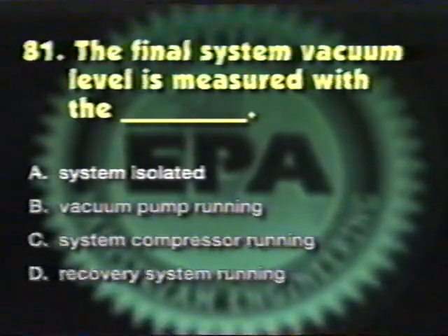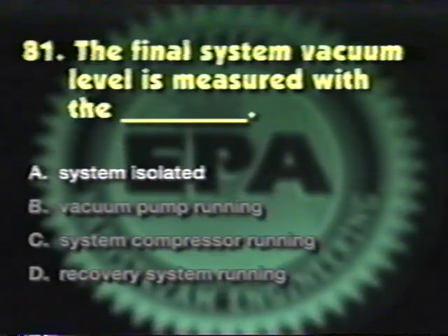The correct answer is A. The final system vacuum level is always measured with the system isolated and the vacuum pump turned off.